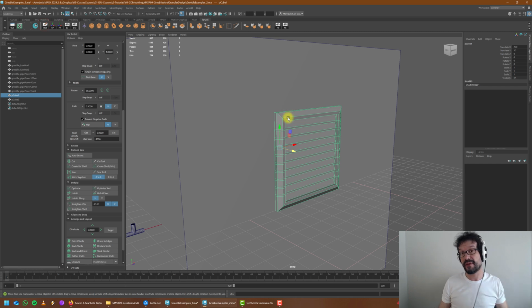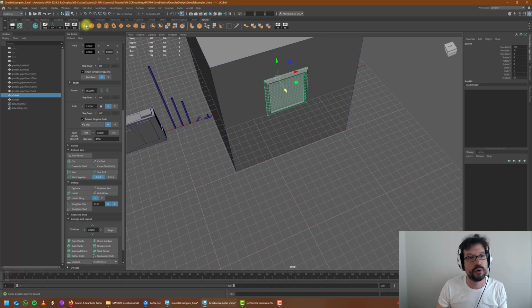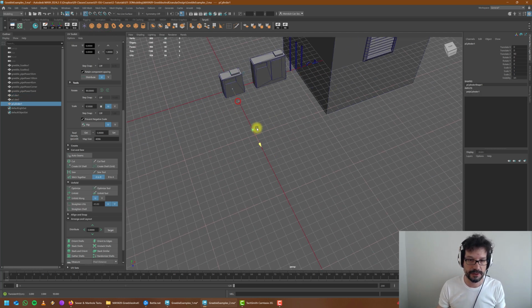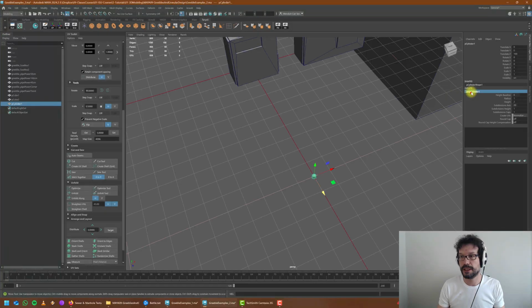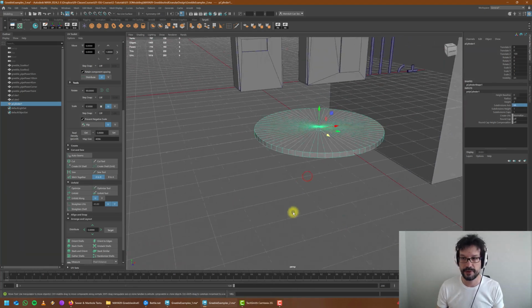You can do similar things with manhole covers as well. For example, imagine you're designing a manhole cover. Let me really quickly demonstrate. I'm not going to put so many details on it. Let's design a manhole cover really quickly. Let's give it a radius of 30, and a subdivision axis of 64, and it has a height of right now 2.